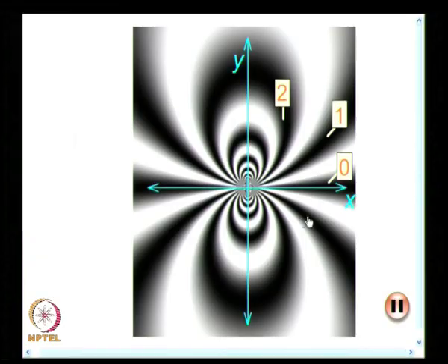See, in none of the problems in theory of elasticity do you really question the stress function. You take a stress function, then look at sigma x, sigma y, tau xy, and satisfy the boundary condition. In this case, we have done all that: we have taken a stress function, it satisfies the biharmonic equation, and we have looked at the boundary condition, it satisfies all the boundary conditions. So, we have not made any mistake in the mathematical analysis, but finally we are getting a solution. I am sure you have already seen the photoelastic fringes, we would see them again. It is nowhere compared to that.